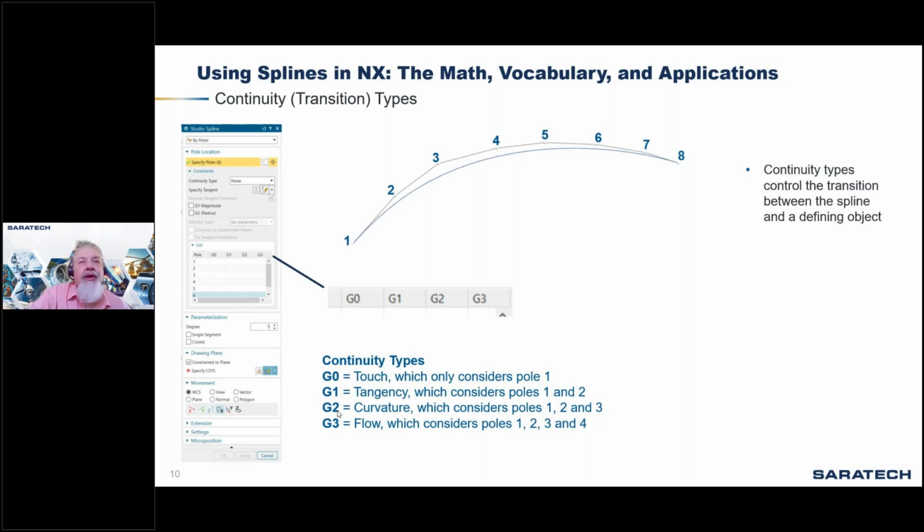And you're going to notice that when you're using curvature, it's going to consider a bit more of that curve. It's actually going to consider how it's created radially, or how that comes about. And if you remember the conic that I showed you a couple of slides back, that used 3 poles to do that. So that gives you an idea there that we're actually considering curvature.